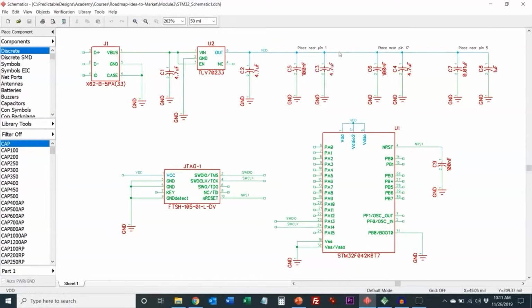And that's just so that any disturbances on the supply line don't necessarily impact the microcontroller. And then also these supply a local temporary storage of energy. All these capacitors will be placed near the supply pins of the microcontroller, so that if the microcontroller needs a sudden burst of current and the linear regulator, which may be far away, doesn't have quite time to respond yet, then that current will be temporarily supplied by these capacitors that will be placed close to the pin.